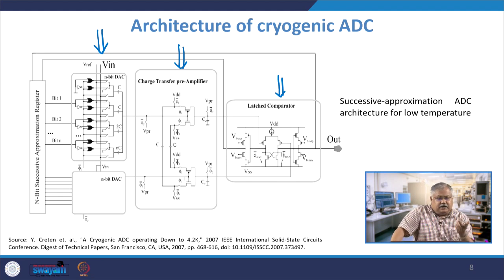So, the DAC will convert digital to analog signal, which is basically done here, and then the subsequent comparator, and this output goes to a standard ADC in a sense, for the cryogenic ADC. Now, this is an n-bit DAC which you see, and this is an inverter here, and these are all exclusive OR gates.